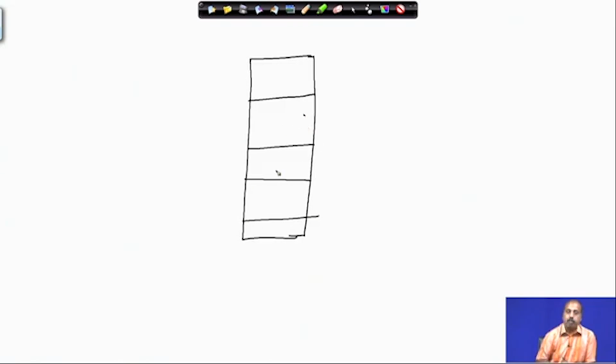Say this is segment 1, and from segment 1 I want to transfer to segment 2. If segment 1 and segment 2 are non overlapping, then I can copy this byte here, then the next byte at the next location, and go on like this. Or I can do it the other way also: start copying from the bottom, first copy this one here, then this one here.